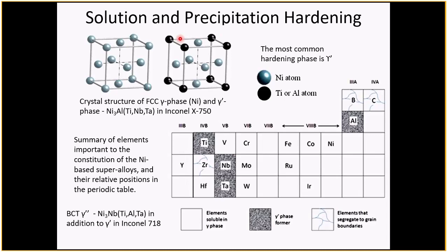That makes it doubly hard for a dislocation to glide, because not only does it have to shear through the atoms, but it also has to create a stacking fault. That additional energy of creating that stacking fault, or antiphase boundary, as it's normally classed, makes that material harder.